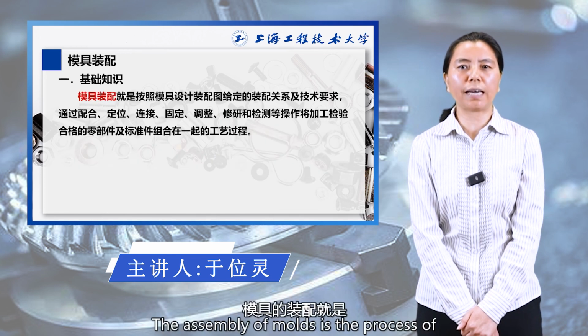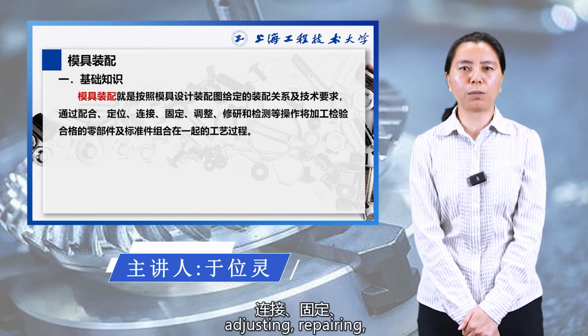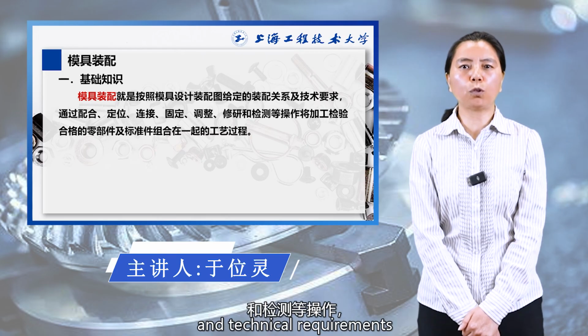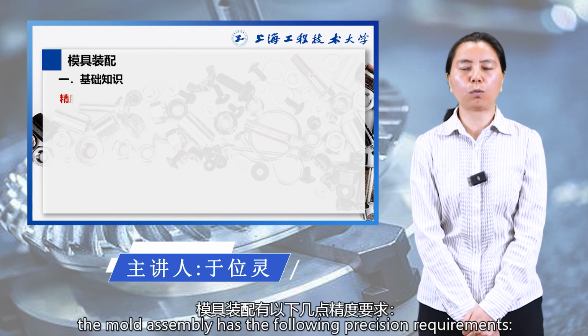The assembly of molds is the process of combining qualified parts and standard components through operations such as fitting, positioning, connecting, fixing, adjusting, repairing, and testing according to the assembly relationship and the technical requirements given in the mold design assembly diagram. In order to ensure the quality of the mold and its formed mold parts, the mold assembly has